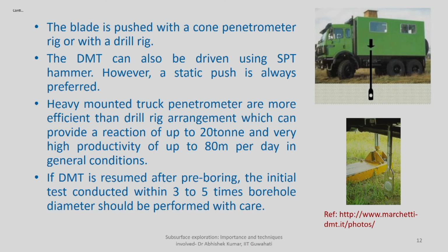Again, in this field setup, because every time you have to push to deeper depth, the reaction frame should be sufficient to penetrate deeper layers. The blade is pushed by means of a cone penetrometer rig or a drill rig. The dilatometer can also be driven using an SPT hammer. However, a static push is always preferred. Heavy mounted truck penetrometers are often more efficient than a drill rig arrangement, providing a reaction of up to 20 tons and very high productivity of up to 80 meters per day. So you can go up to 80 meters.